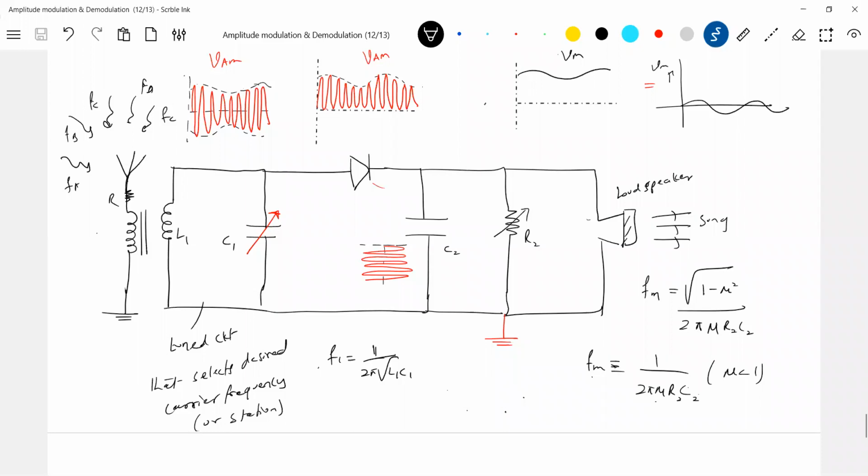Is it okay? So this is called an amplitude demodulator. What all do we have? Tuned circuit, diode, low pass filter, which passes low frequencies and blocks high frequencies, and the loudspeaker. And this filter should satisfy this equation for successful recollection of the modulating signal. Sir, what happens if this equation is not satisfied? You may hear the song, but a lot of disturbance and noise will get added, it will be distorted. Something will be missing from the complete song, here and there some breakups and distortion. We just call it distorted.